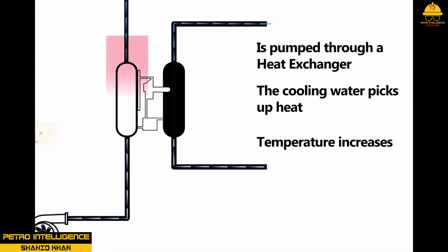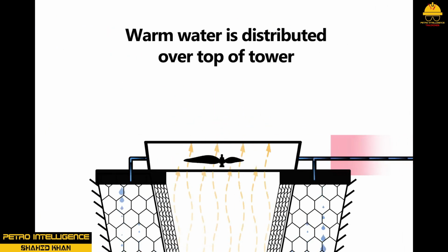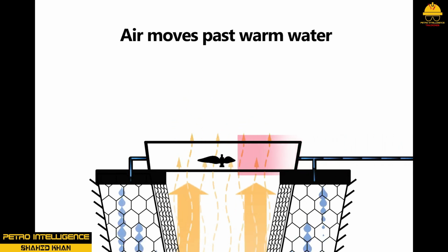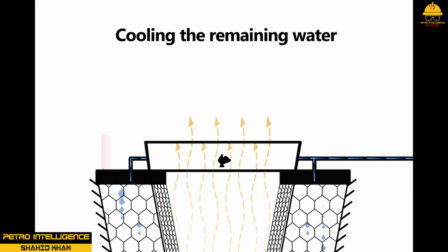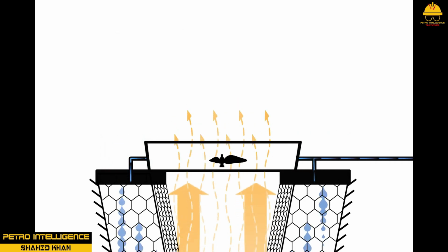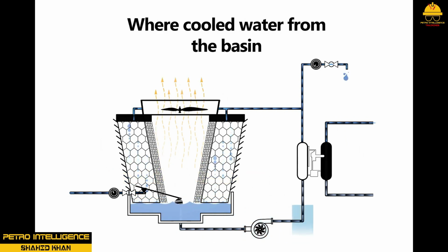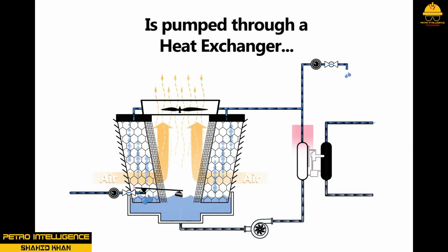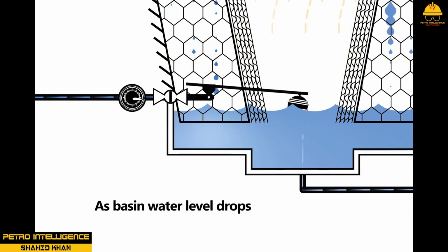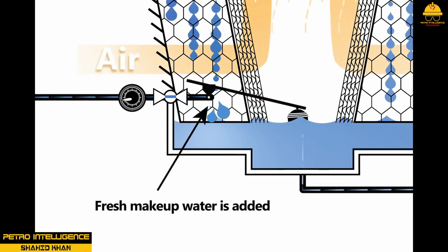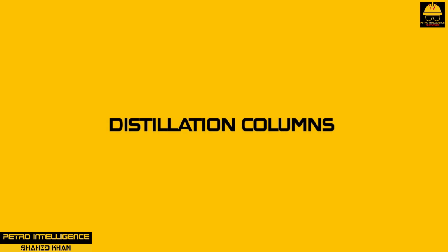As the hot water goes into the top of the cooling tower, it enters a water distribution header, from which it is sprayed over the internal components, fill, of the tower. As the water falls on the splash bars, cooler air contacts the water. This process removes 10 to 20% of the sensible heat that can be measured by a change in temperature. Another 80 to 90% of the heat energy is removed through evaporation. The cooled water collects in a basin at the foot of the cooling tower, where a recirculation pump sends it back to the heat exchanger.